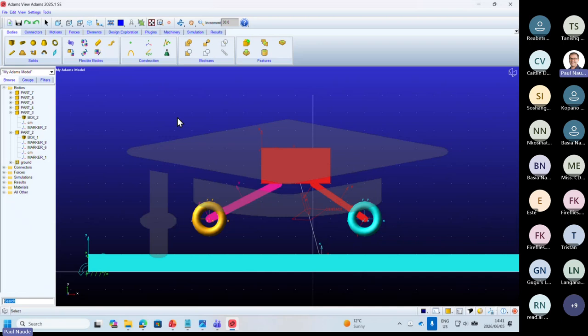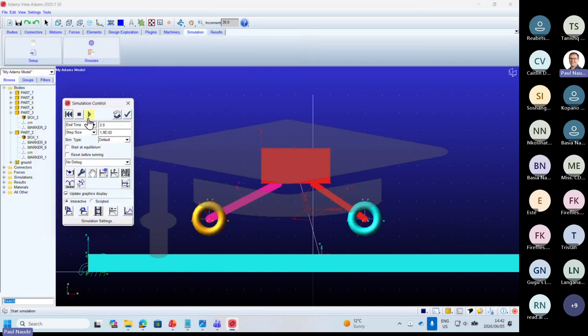And it is at this point that I want to highlight the fact that we don't need detailed CAD to develop a concept or a model. So if you have an idea of how you would like the suspension of your rover to work, you can very quickly generate it here. And the nice thing about this geometry is if we move any of these markers, we can easily readjust the whole model. So if I just press run now, you'll see everything just falls except for the body of the rover. The other things haven't been connected.